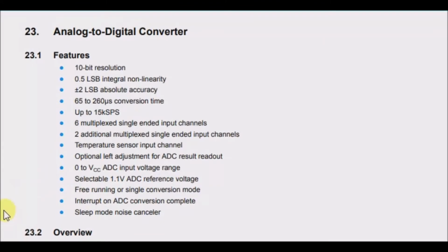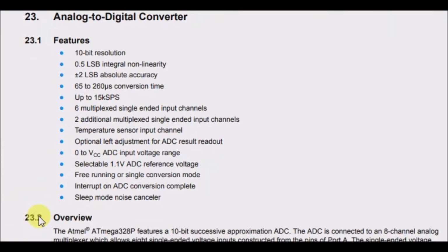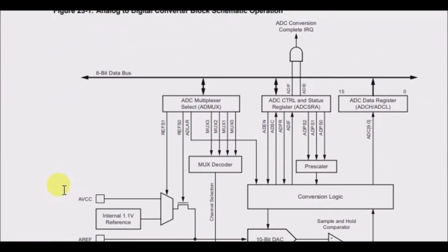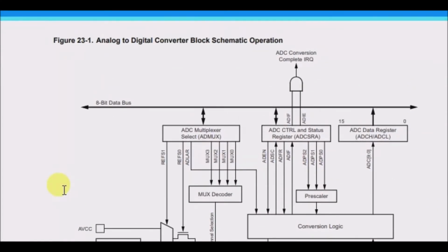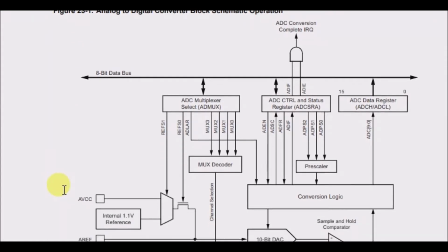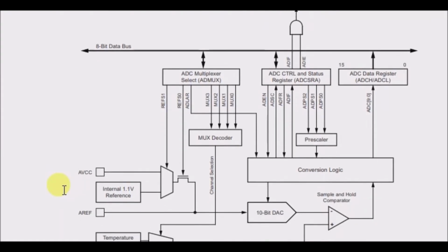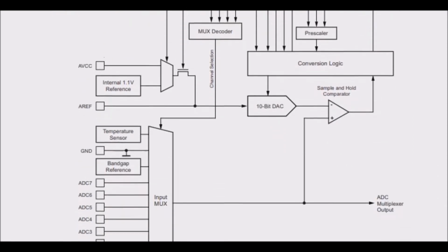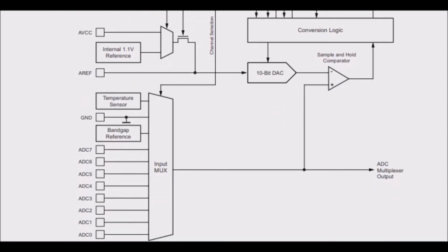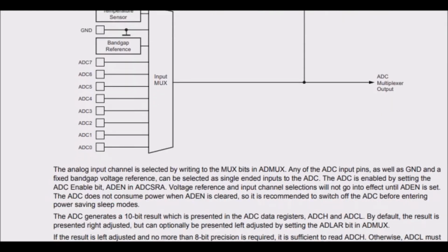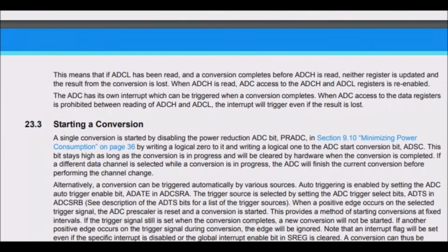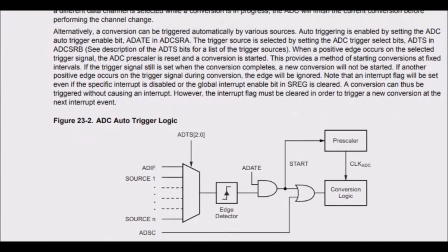You see, the Arduino does have a built-in analog to digital converter, ADC, but the Arduino does not have a built-in digital to analog converter, DAC, although it can pulse width modulate, PWM, a signal to achieve a similar output.